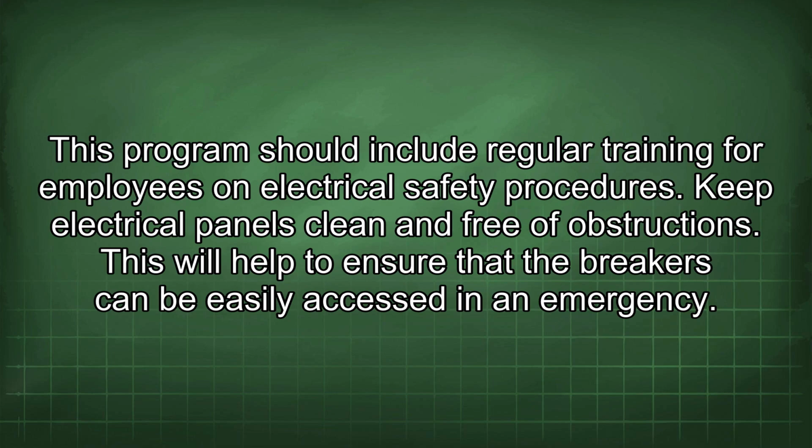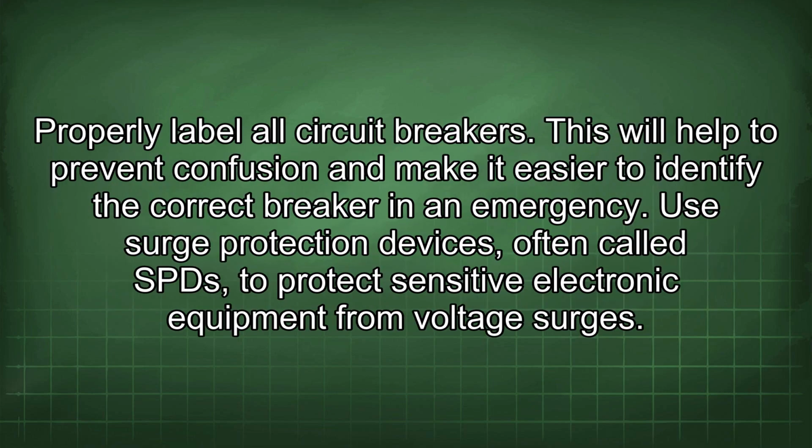Keep electrical panels clean and free of obstructions. This will help to ensure that the breakers can be easily accessed in an emergency. Properly label all circuit breakers. This will help to prevent confusion and make it easier to identify the correct breaker in an emergency.